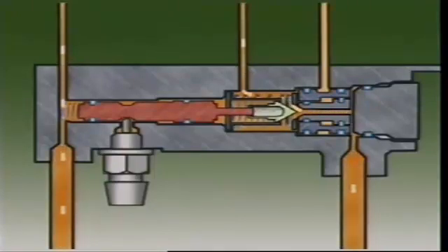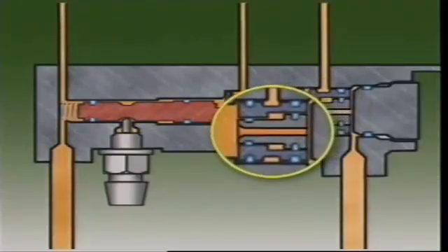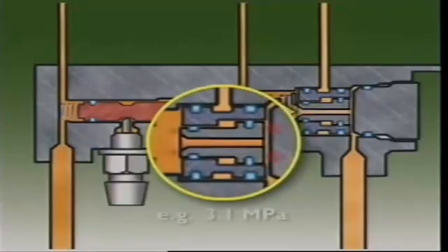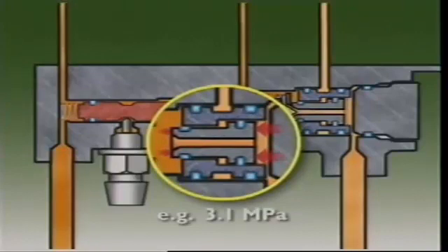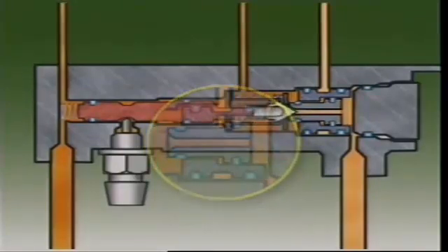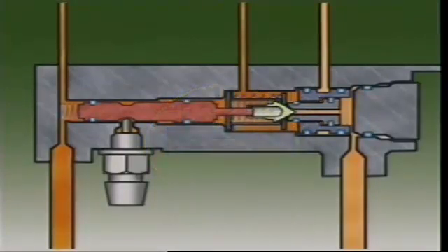In heavy braking, master cylinder pressure can reach a valve's crack point. The pressure applied to the two different areas of the poppet piston creates unequal forces. That moves the poppet piston against the large pressure spring. This action holds the conical section of the valve against the seat, which limits the pressure increase to the rear brakes.